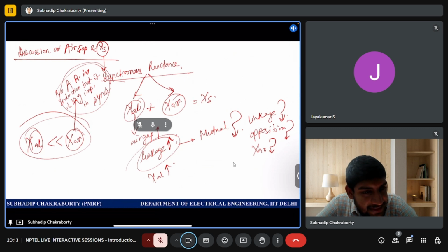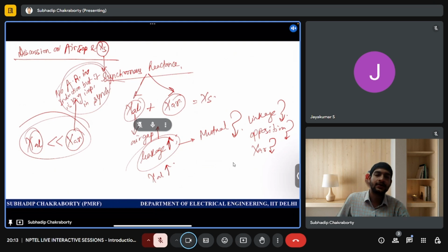For a doubly excited machine, we can control the effect of armature reaction. Or in other words, we can control the effect of power factor. We can control the power factor. Okay. But there is armature reaction. We'll just see the MMF diagrams, how it all happens. But please remember, armature reaction is a dominant phenomenon in a synchronous machine.